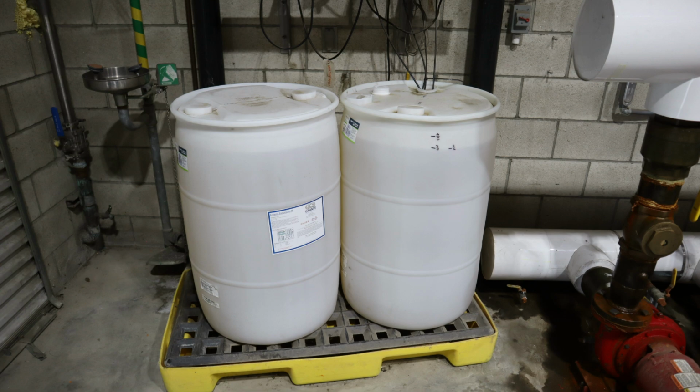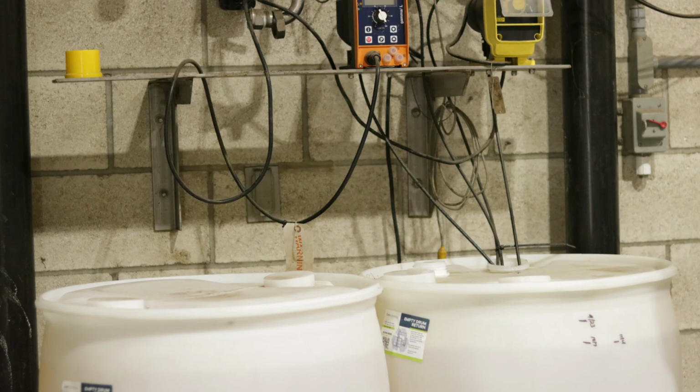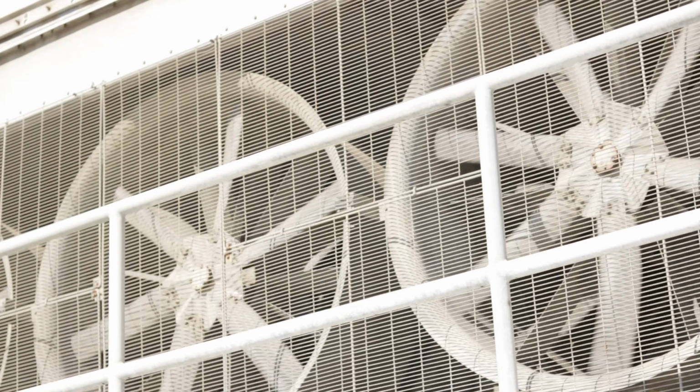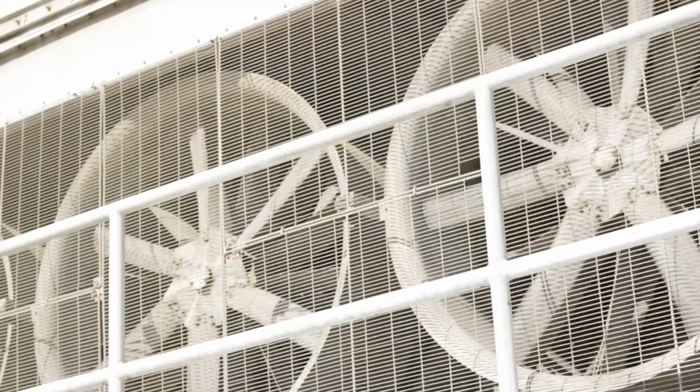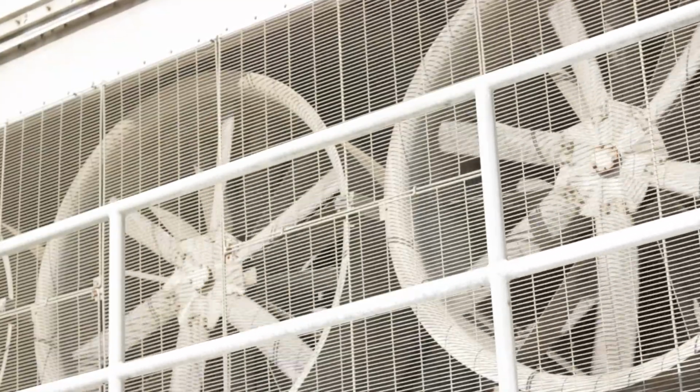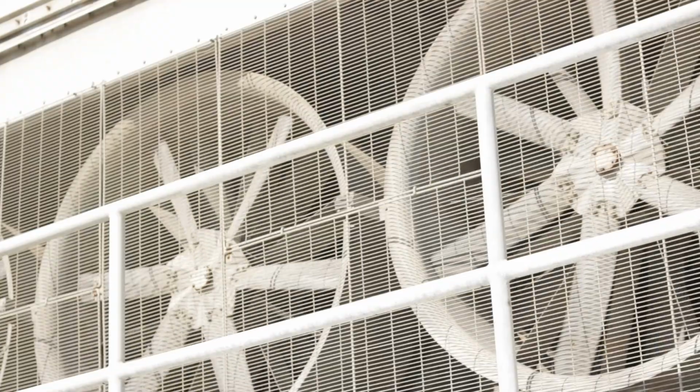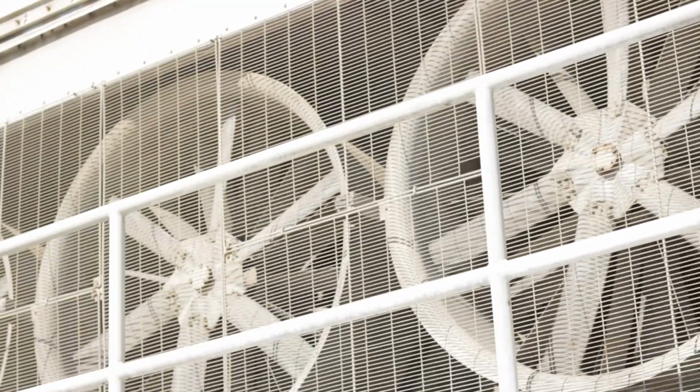Passivation involves circulating water with a pH between 7 and 8.2 for 4 to 8 weeks, or until new zinc surfaces turn dull gray in color. Proper execution of passivation contributes significantly to the lifespan of an evaporative condenser. Condensers using stainless steel tubes do not require passivation.